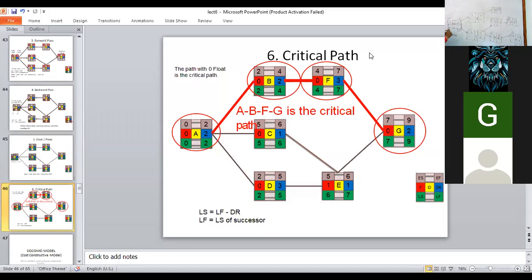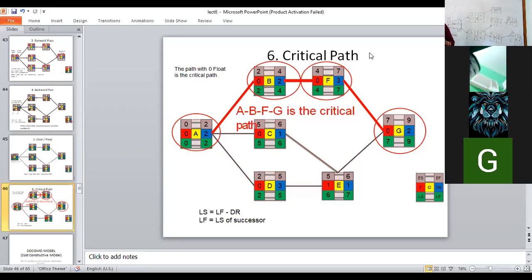So we are done with early start and early finish for every activity. Now this is called the forward pass. We are moving forward. That is why we have taken 12 here. We have taken a maximum, of 12 and 13.